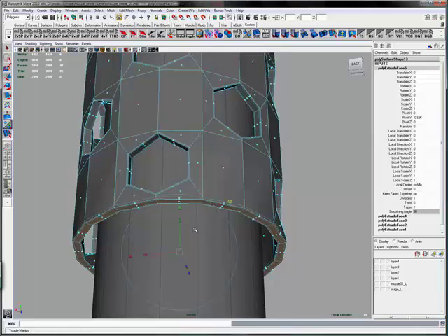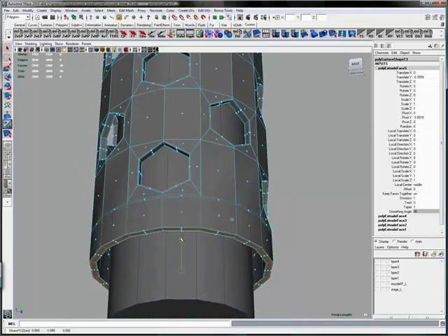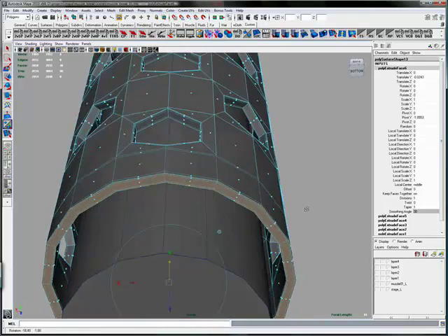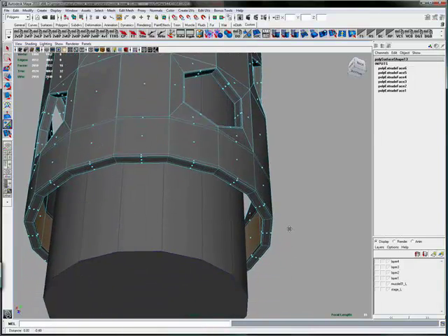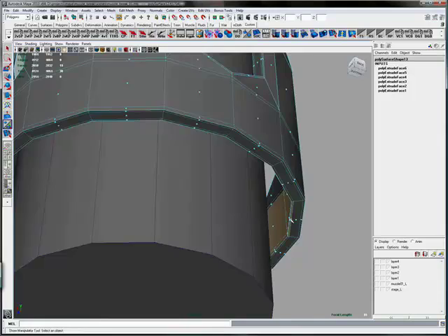So the first thing I'll do is a small offset so that we hold the edge on the inside wall. We'll scale it out one more time, and then one more time to tighten up the end of the barrel there. Now all we need to do is select those interfaces, and we'll scale them in to snugly fit around the barrel.